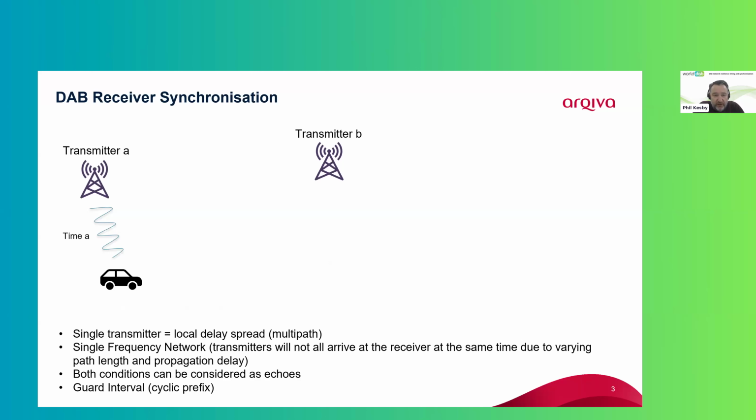Often that signal is subject to multipath, which means we're going to have echoes of that transmitter, or of that service, being received at the receiver, so we've got multiple versions of the symbol. What makes it even worse, if you press the down key, please, Michelle, is that we could have a second transmitter in our SFN with a different propagation delay being received at the receiver. So how does the receiver cope with this condition where you've got multiple versions of the same symbol being received?